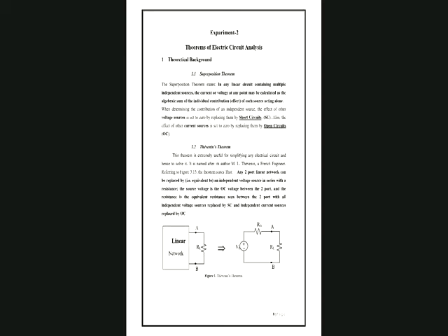So whatever the two-port network may be, you can convert it by just finding the VThevenin, the voltage across the entire two-port network, and connecting the load, finding the RThevenin, which I will show you in the experiment, and connecting this RThevenin in series with the load resistance.